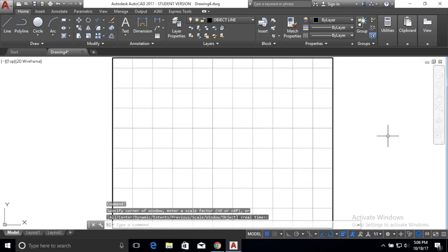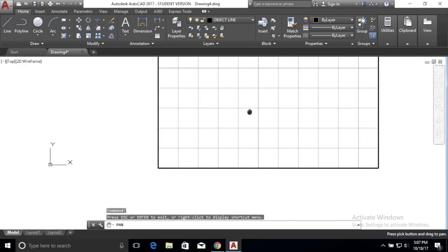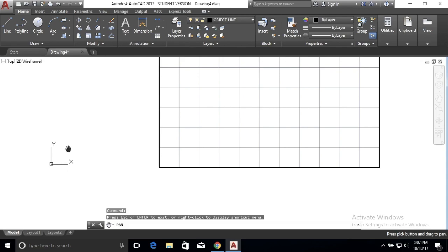So in our previous lessons, you've been using the cursor to place objects, but in this lesson, you're going to learn how to place objects in specific locations by entering coordinates, and that's called coordinate input. To start with, we have an x and y coordinate, so y being up and down and x being left and right. Just like a graph sheet of paper that you might use in math class, the coordinates are x comma y, or the x, which is left and right, and then the y, which is up and down